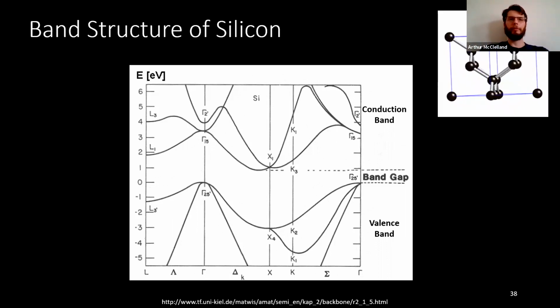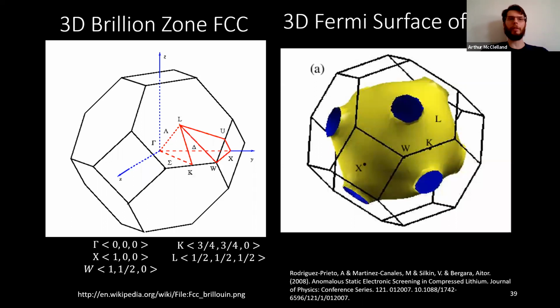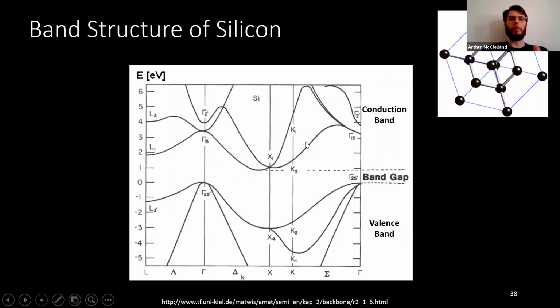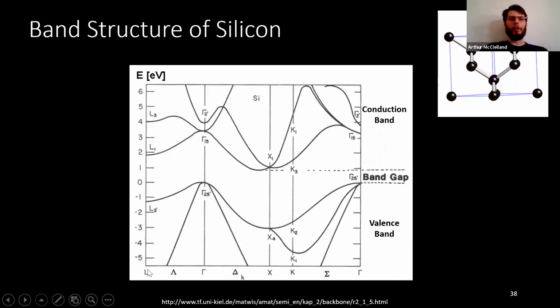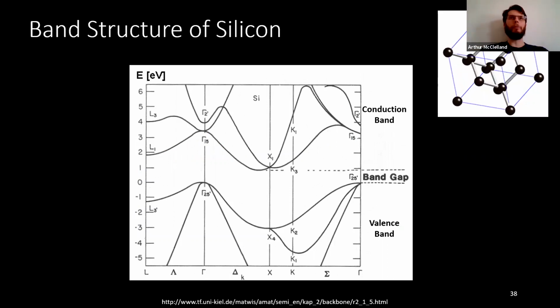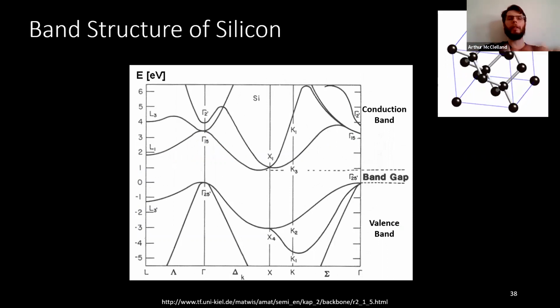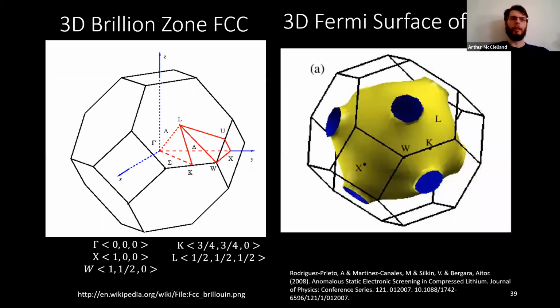And of course, this representation of the band structure of silicon is in 2 dimensions, but the silicon structure is in 3 dimensions. So it should really be a more complicated surface. It gets very hard to think in these 3-dimensional spaces. So that's why we usually use this 2-dimensional space, which is unfolded, sort of like a map is the unfolding of a globe. Here, this band diagram of silicon is like the map of this globe.